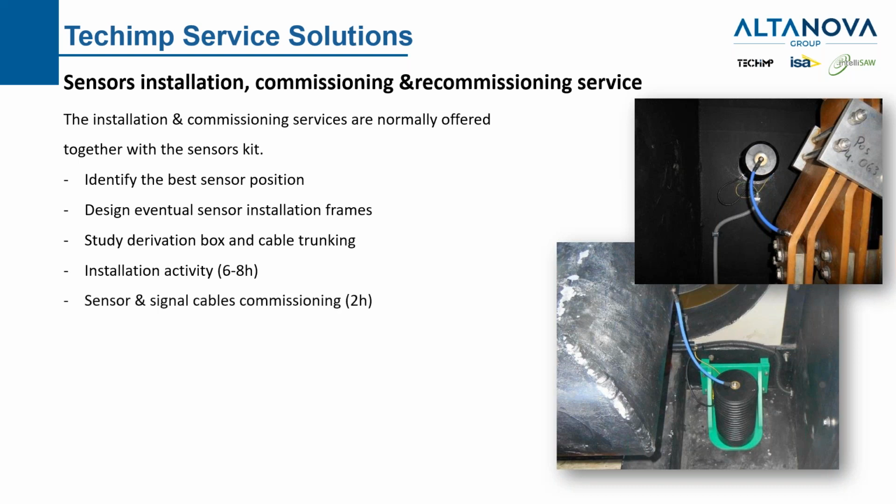And then we have a sensor and signal cable commissioning test to check that everything is okay, the sensitivity is good, and there is no mismatch in the phases. That, believe me, is something that happens, especially with sensors when you don't know who installed them. And we also provide services for sensor recommissioning.